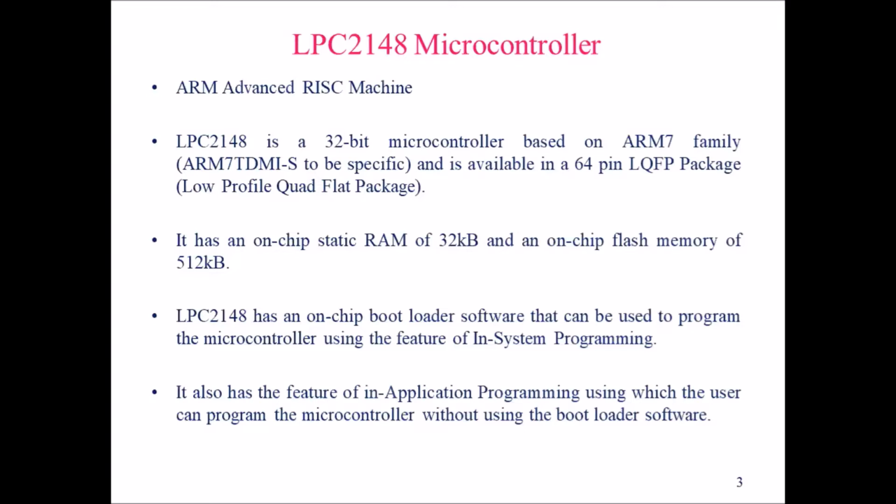Again, it has on-chip static RAM. Here in the microcontroller, every component is embedded on the system on chip, that's why it is called SoC, which stands for system on chip. Every component, including RAM, ROM, and the ARM processor, is embedded on the single chip itself.